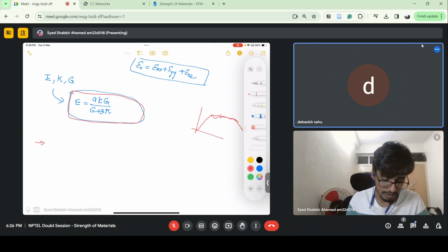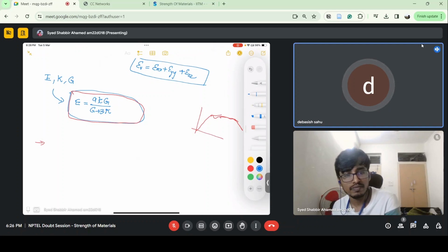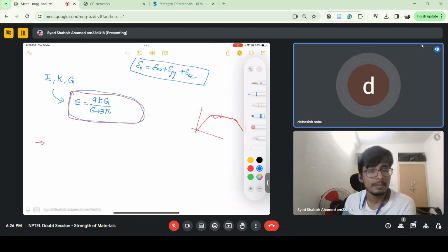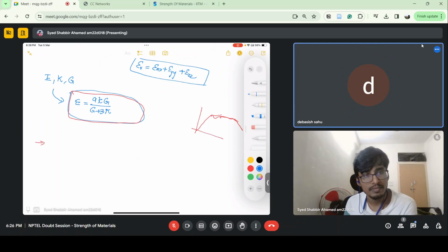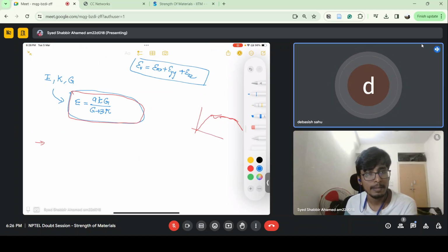Understand, sir. That means the graph is remaining the same, but if I change the specimen dimension, only the magnitude changes, the strain magnitude and the stress magnitudes. Stress will also not change. So instead of 200 gigapascal, it may break at something else because I increase the area.